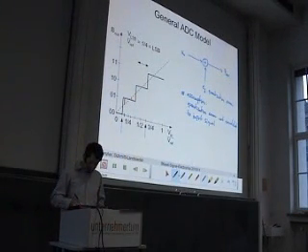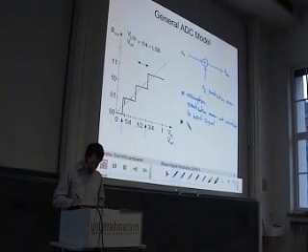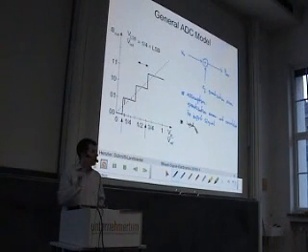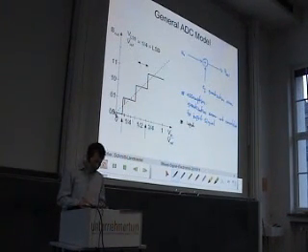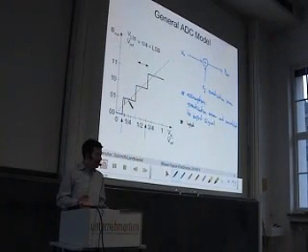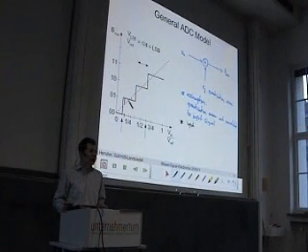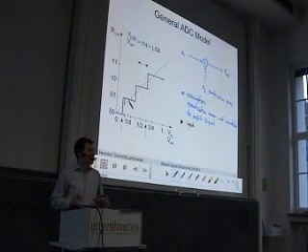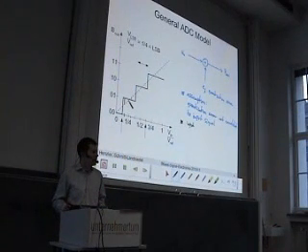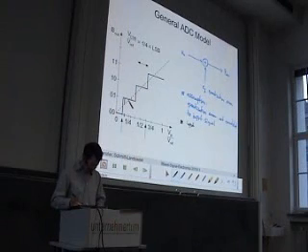However, if we assume that the input signal changes very fast, and the change is also quite large, then we jump around on this step function considerably, and we get lots of different quantization errors, and at the end it seems to be a random quantization error which is not correlated to the signal.